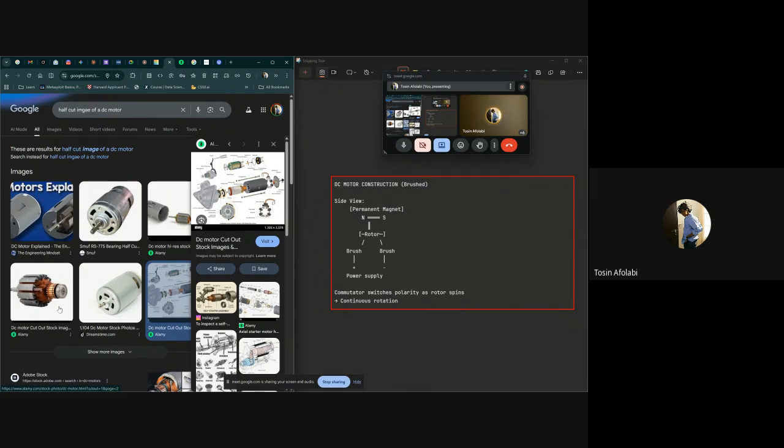And one thing to know is the frequency of the change is 490 hertz. That's the Arduino default. The motor sees the average voltage that the Arduino sends due to inertia. The motor can't react to individual pulses at 490 hertz because that's too fast. So the motor responds to the average voltage. By varying the duty cycle, we can control the speed smoothly.